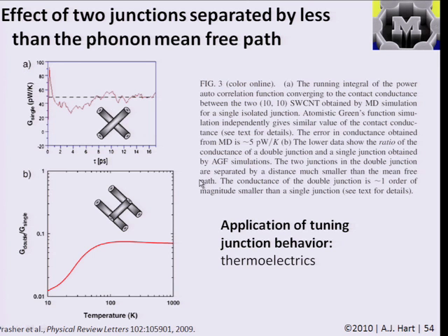So just this physical constriction of the vibrational modes in the material was causing a dramatic decrease in the thermal conductivity. So in this case, you have this three-dimensional network of thermal conductors where you're trying to get heat from one side to the other, and no matter where the heat is going or can go, the fact that it is in contact with a whole bunch of other tubes is dramatically decreasing the ability of the material to transport heat. And this is another kind of limiting case where we see how the scaling of properties is very different as we get to large number densities and particular length scales.